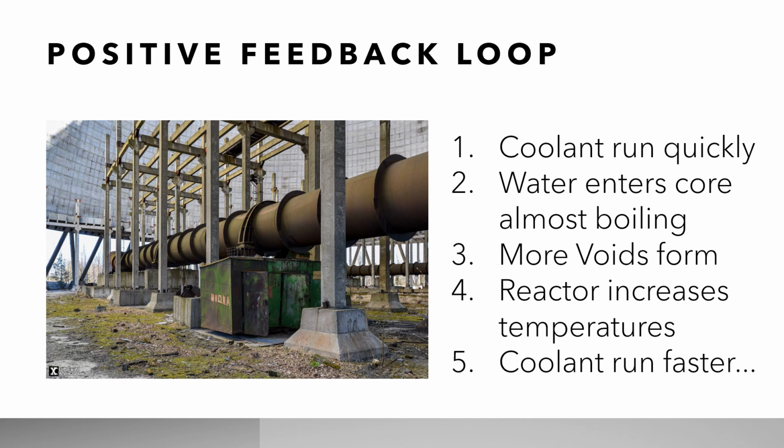The coolant was also being run extremely quickly, which was a bad thing, because coolant would enter the core near boiling point, and some of the water would form voids in the pressure vessels. These voids moderate neutrons worse than water, so the reaction would hasten, which would result in higher temperatures, which would result in a positive feedback loop thanks to continuously increasing coolant flow rate. However, the test was a success though, ignoring all the alarms that went off during preparations.